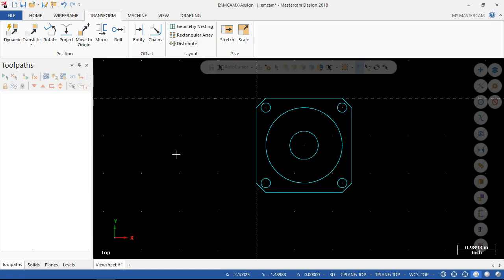We're always starting with that, and whether it's a personal 30-second conversation or you sit down and go, we're making thousands of these. I really need 3 blocks coming across so that I can hold 3 of these in the vise at one time, and we can make 3, and then I'll write into my operating MOT, the machine operations and tooling, that the second step after this is, well, first is that we saw, second is that we run this first op, third is somebody gets to stand at the bandsaw and separate them, and then cut them into 3 pieces. Then we flip them over and machine the backside. And so, we got to think about some of those strategies.